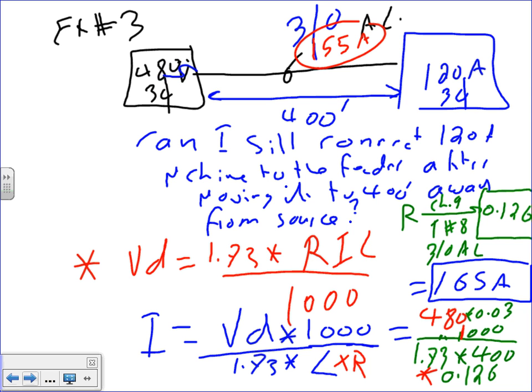No matter what your voltage drop calculation comes up with, you cannot exceed what the conductor can carry under table 310.16, under whichever category, 60-degree or 75-degree. But we did the calculation right, guys, right? Everybody? Okay, so our conductor was big to start with, so we don't have a problem.